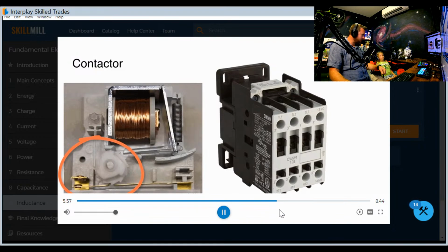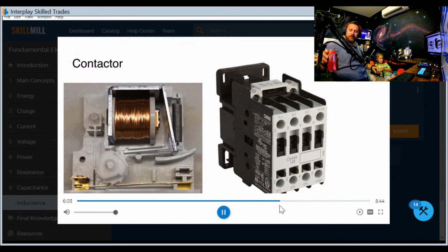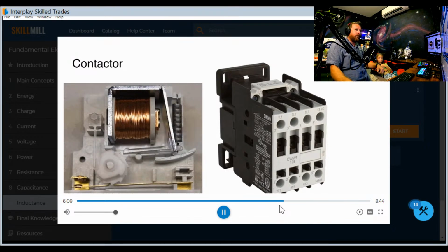until released by another pulse of signal power. This can be useful where control power might be unreliable, or where you want to reduce power consumption, or where you just want to control another circuit with a momentary push of a button instead of having to keep the coil energized the whole time.